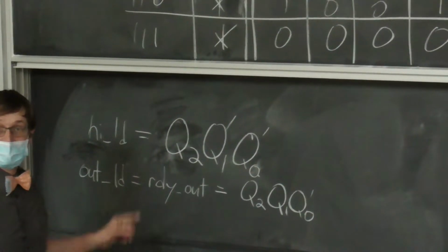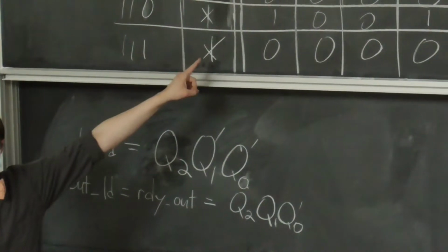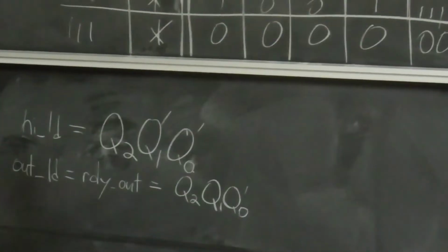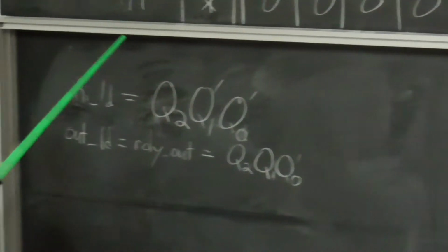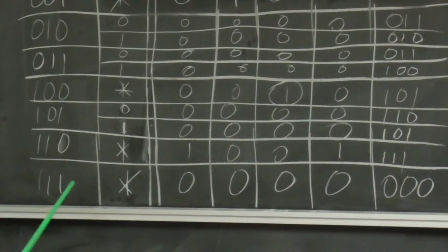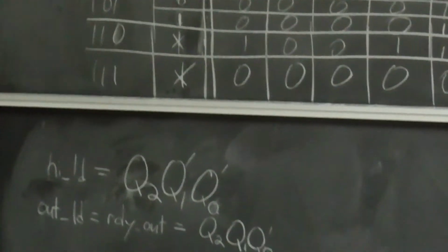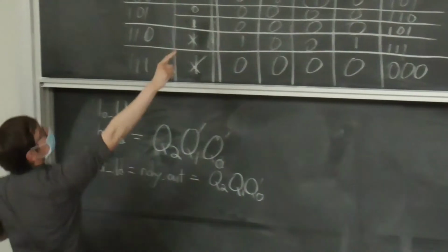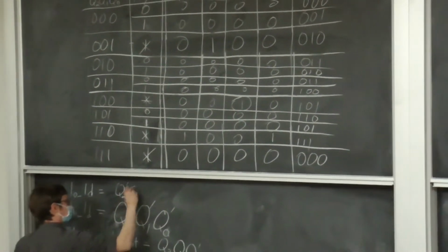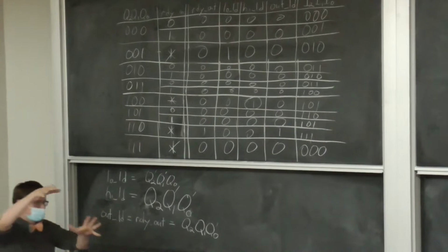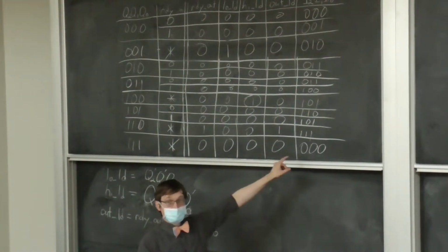Because the ready-in signal doesn't matter, all you have to do is derive the signal purely from some kind of combinational logic on the state elements themselves, the state register, the register that shows you which of the bubbles you're on. In addition, if we wanted to do low load, we can read across. It's not Q2, not Q1, Q0, right? So you can imagine the circuits in your head, I hope.